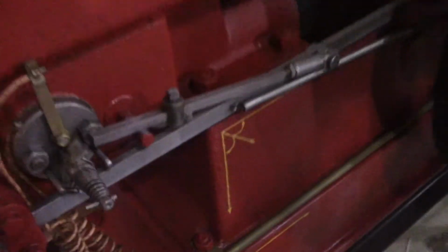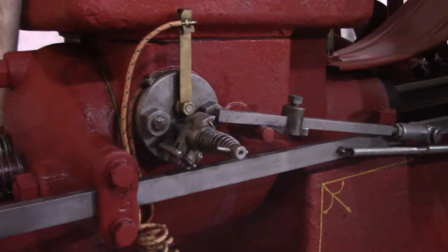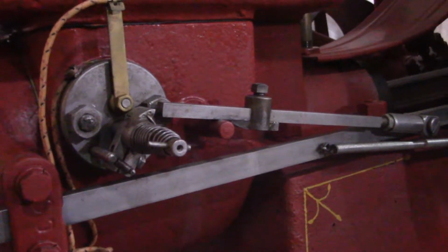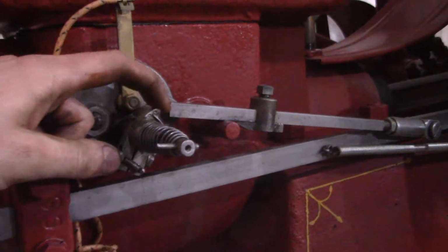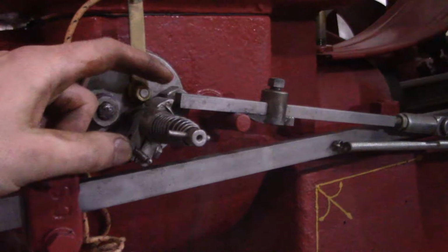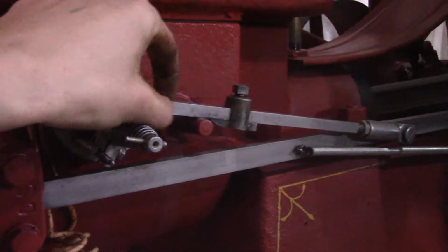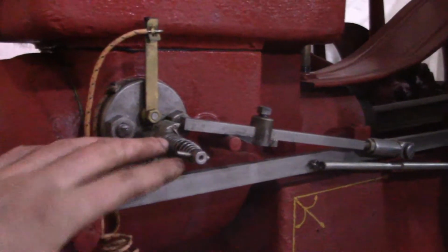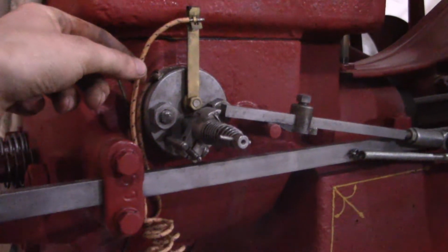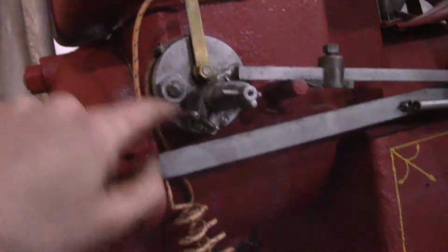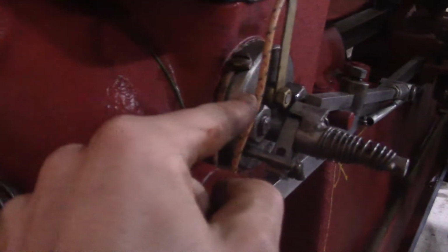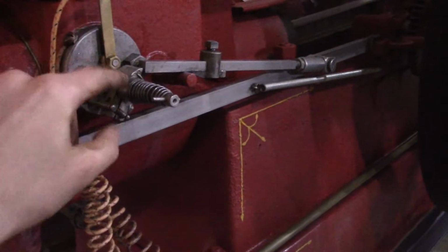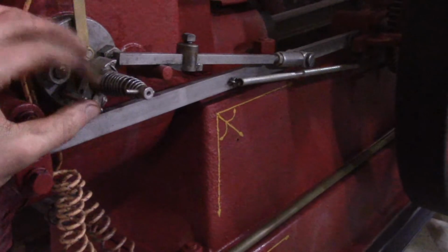Now you'll have to bear with the somewhat dark lighting, but this should illustrate what an igniter fired engine looks like. As you see, here's the external trip for the igniter, and then here is the trip rod. The trip rod is attached onto the exhaust valve push rod, and that's it. There's one hot wire, and then a ground wire just attached onto the frame ground, and that goes to the contacts inside.